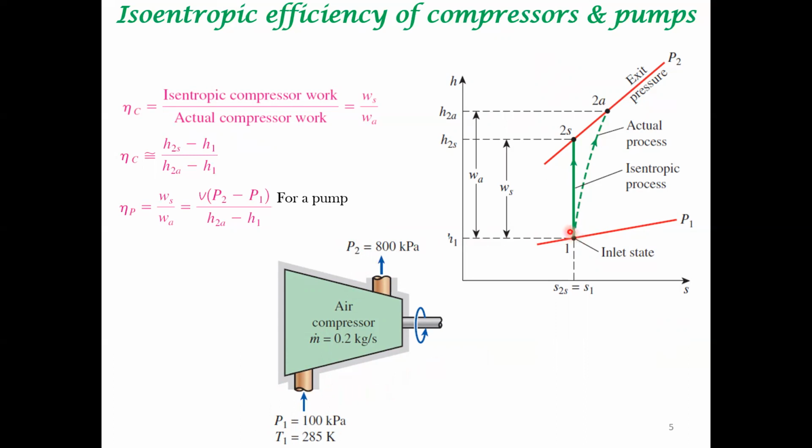For the ideal system, the minimum work that needs to be incorporated is under isoentropic condition. Again, neglecting the kinetic energy and potential energy changes, the work can be obtained from the difference in enthalpy. The actual compressor work is greater than the minimal work that needs to be incorporated into the fluid stream. The minimal work is obtained from the difference in enthalpy in the following manner.